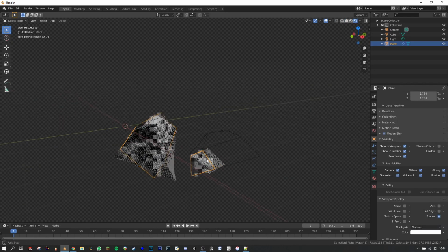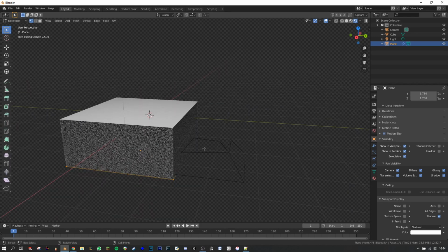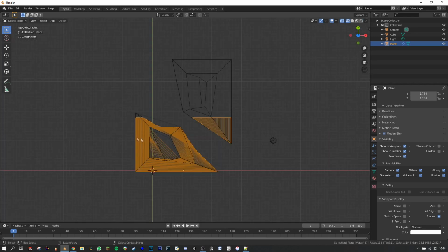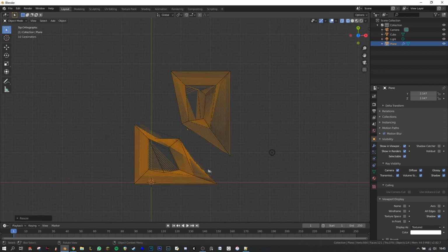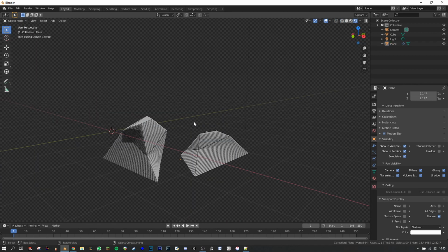If it's cutting off the side slightly, make sure that your plane is covering your entire Boolean object. You might have to scale it up slightly to do this. If you want to change the number of sheets the object is made of, just increase the distance in the array modifier.